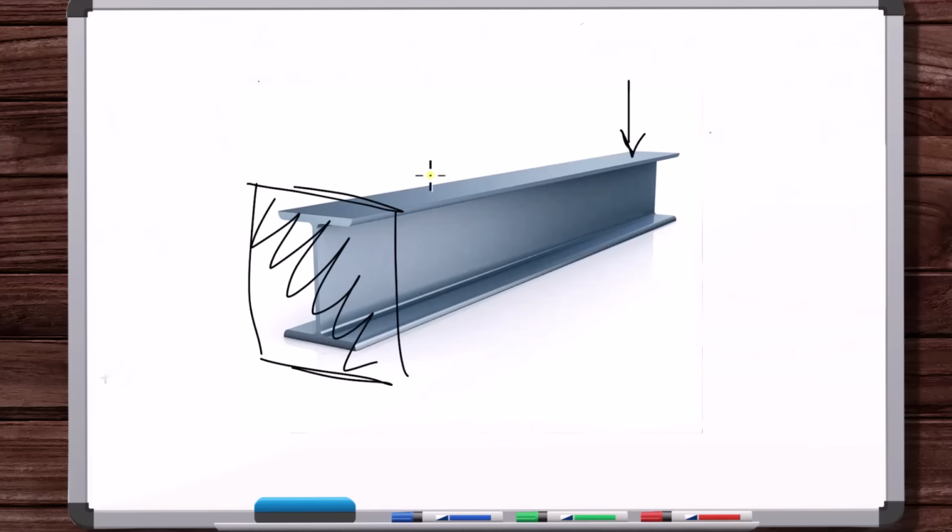Here, those are internal forces. And internal forces in a free body diagram, you don't put those in the free body diagram, because here, we made that cut before, and we removed that adjoining face. Now that adjoining face is part of this. So at this point, yeah, these forces are still present on that face. But now the other face is part of the free body diagram, and it's Newton's third law. The other face is experiencing the exact same forces, but in the opposite direction.